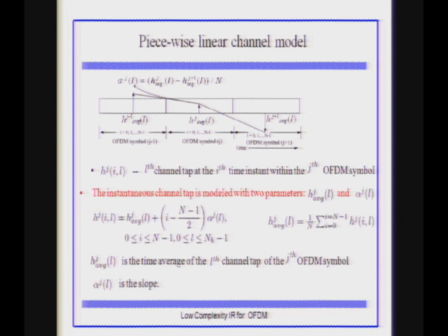Have you seen other models? Yes, there are. At very high Dopplers, say L getting to the realm of 2 and 3, people try to fit different functions, say Slepian functions. There are many other complicated models, such as basis expansion models, BEMs, that are used at very high Dopplers.